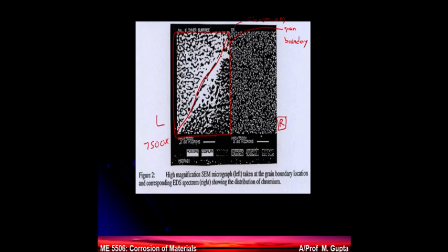The fundamental of intergranular corrosion is that if it is indeed a case of intergranular corrosion, as he has rightly said, where are the precipitates? The precipitates are missing, and there is no chromium depletion. There has to be a chromium depleted zone here, if you recall that picture which I explained to you.